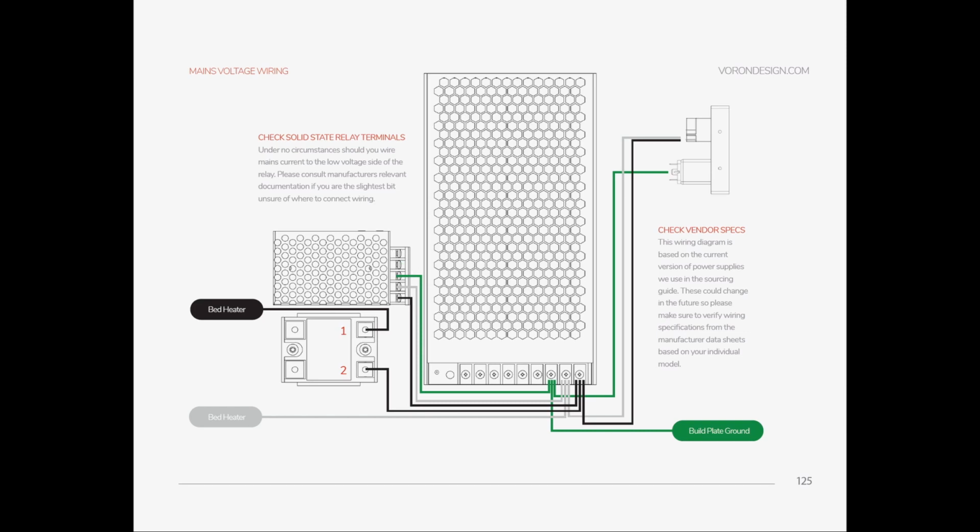So you can easily say that, okay, there is an issue in the wire which is between my small power supply and the source, I mean the terminal. So you can easily diagnose it. Later on, for example, after unplugging your cable, you can do a continuity check with these wires and see if the wire is broken or something. Or you can check the input in here, 24 volts. If it is coming 24 volts and there is no output, that means your power supply is not working, etc.